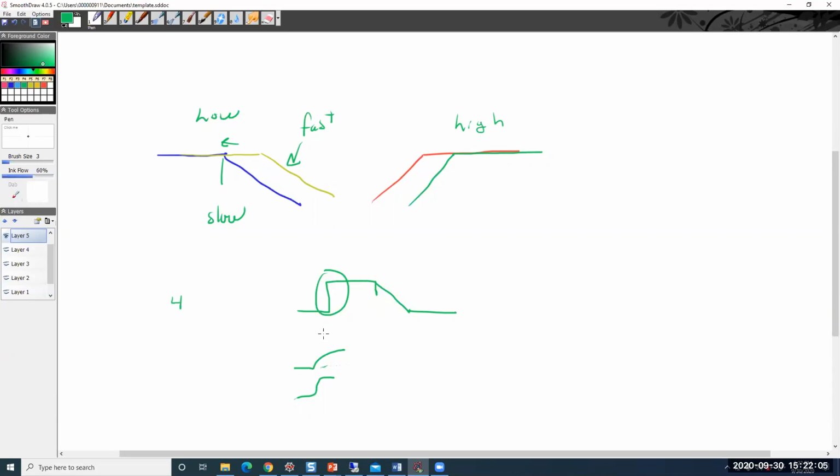That's how you could tell between the low pass features and the high pass. One's going to take a long time to dissipate, one is going to take a shorter time. That's omega naught, which is 1 over tau, so it's inverse. The slow one takes a longer time. So this is slow, and that is fast.